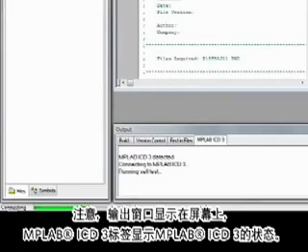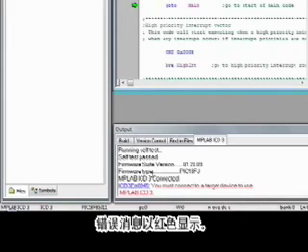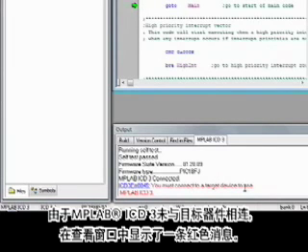Notice that the output window is displayed and the MPLAB ICD3 tab is showing the status of MPLAB ICD3. The output window is used to communicate messages from MPLAB IDE to the user. Error messages are displayed in red. Since MPLAB ICD3 is not connected to the target device, a red error message is displayed in the watch window.